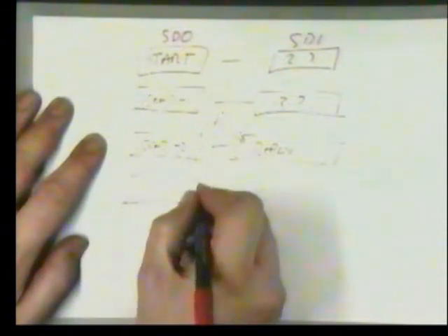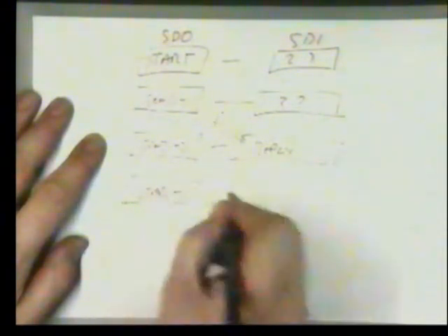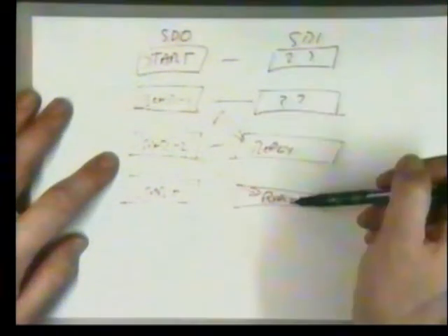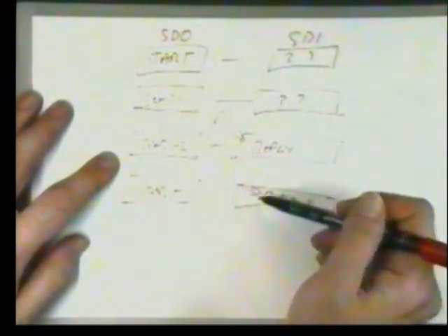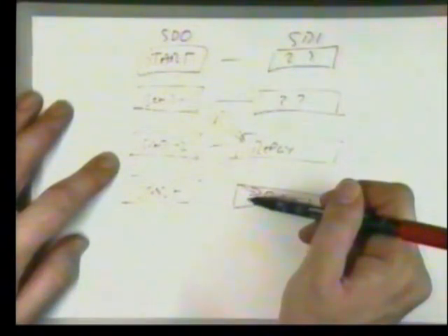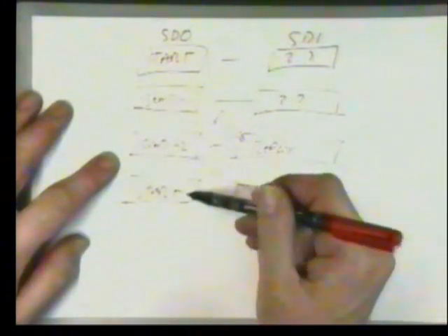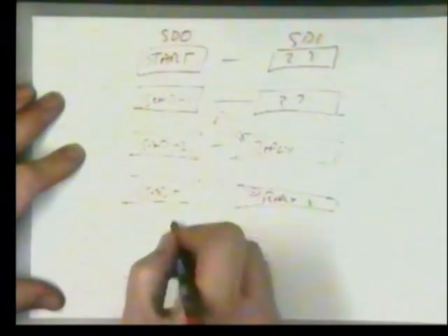Now we can start the next conversion. And what would we get back? We would get back here the second part of the reply. So what we've done is we've made use of this redundancy period. We've interleaved these 2 operations to get rid of one of the redundancy periods so we get back the last part of our result when we start off the next cycle. So if we have a program loop that's a nice tight loop, we can get rid of this redundancy.